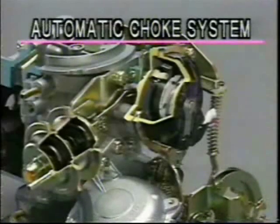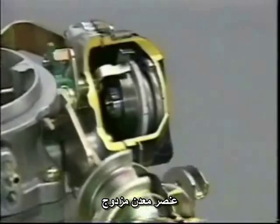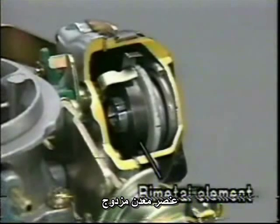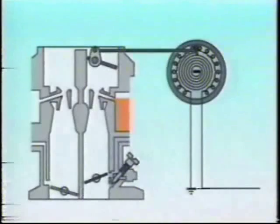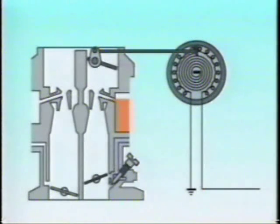At present, as is shown here, the most common type is the automatic choke system. We will also introduce the electric automatic choke, which is currently in use in most vehicles. The automatic choke is controlled by the contraction and expansion of a bimetal element. When the temperature falls below a set level, depressing and releasing the accelerator pedal will cause the choke to be completely closed by the contraction of the bimetal element.